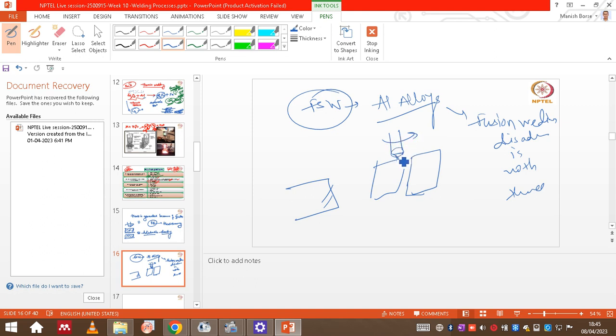Okay, so obviously the parameters are different. That means the shape of the tool or the shape of the profile of the pin which we are inserting, also the travel speed, rotation speed, and what load we are giving, all these factors are contributing here.